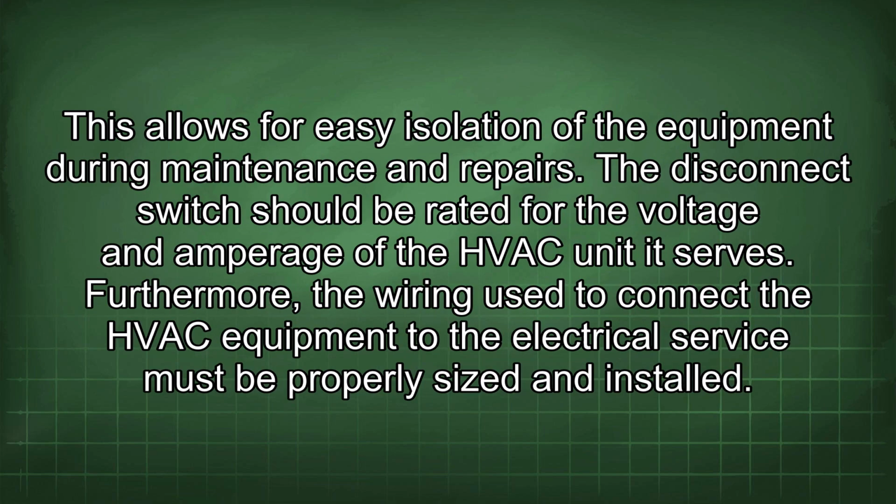This allows for easy isolation of the equipment during maintenance and repairs. The disconnect switch should be rated for the voltage and amperage of the HVAC unit it serves. Furthermore, the wiring used to connect the HVAC equipment to the electrical service must be properly sized and installed.